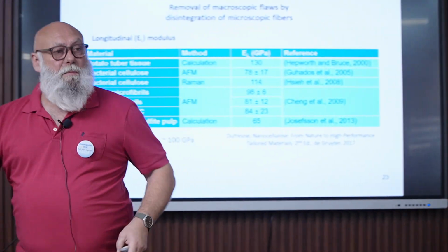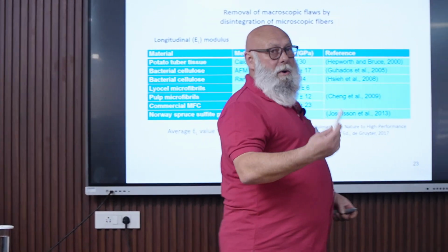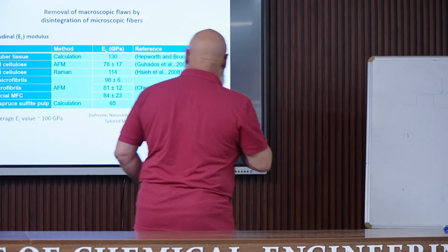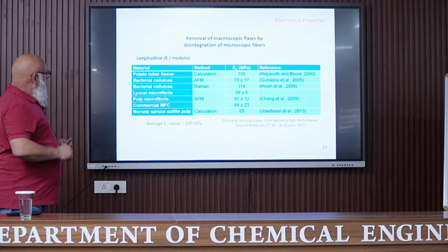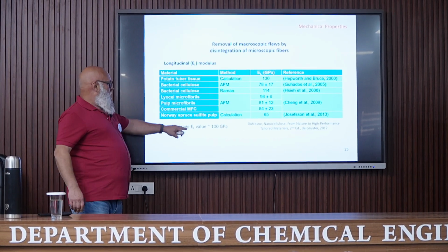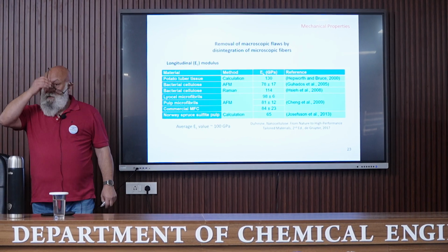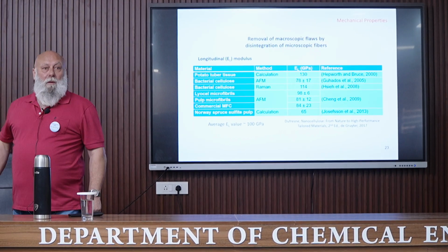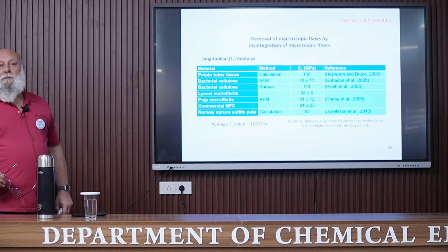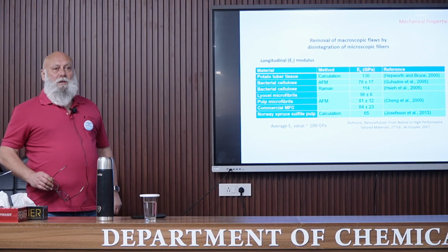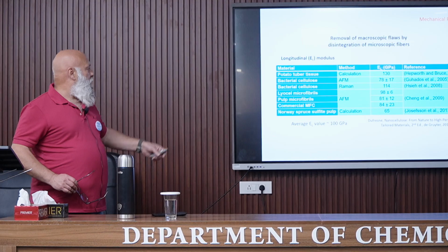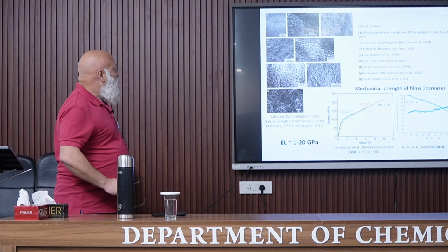From this, it's possible to evaluate or estimate at least the stiffness or the modulus of the material. The average value is around 1 gigapascal. It's a high value, because for glass fibers, for example, the modulus is around 70 gigapascal. We have a higher value in this case.